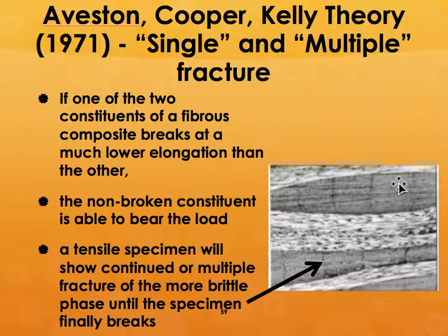Especially if the elongation to failure for the different components is different, you can have continued or multiple fracture of the more brittle phase until the specimen breaks completely.